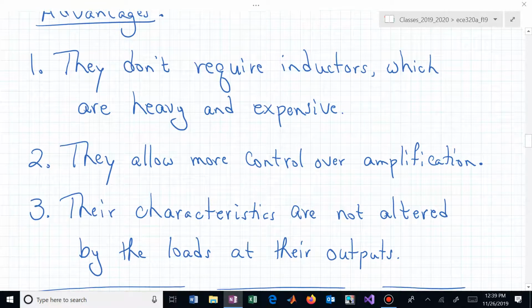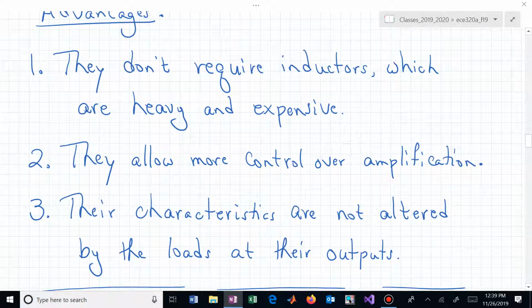And the other nice thing, or an advantage with active filters, is we can start applying resistive loads or some other kind of load to the output of that circuit, and it's not going to load it in the same way as a passive circuit will. A passive circuit, now you load it and you've now messed up maybe the break frequencies that you were expecting, because now you have a slightly different circuit configuration. The active filters allow you to think maybe more in terms of black box building of these subsystems to produce the result that you want.